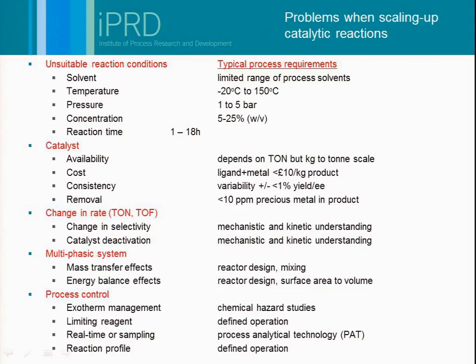Again, one thing that is often not considered within chemistry are phases. So engineers always think about gases, liquids, solids, and how they meet and how they combine. And that has a dramatic effect on the choice of the reactor that you might use. So the way in which you mix these different phases, I'll show you in a minute, becomes very important. And similarly, energy as well, and the removal of, or addition of heating to a process can affect dramatically the way in which you scale up.